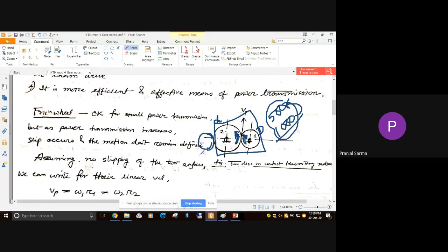But in that case, generally we go for this gear train arrangement, and then the middle gear becomes the idler gear, and it is just changing the direction, as well as, if required, it can change the value also. After that, what will happen if we consider this portion now, the second and third, and suppose this is the third wheel. In that particular case, the second one is rotating in the anti-clockwise direction. So this one is rotating in this particular direction. That means once again we have obtained clockwise direction rotation. So this can be done. Understood?